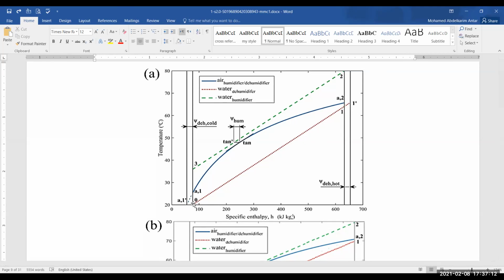So this is something that you can see, and the differences are not large. Having that, the smallest enthalpy pinch values are evaluated actually at the ends, because the differences of enthalpies between the two streams at the end are the smallest. This is the opposite in the humidifier. This is the water which is sprayed in the humidifier, that green dashed line, whereas the blue line represents the air heating. The difference in the enthalpy reaches a minimum value somewhere inside, it's not at the terminals.